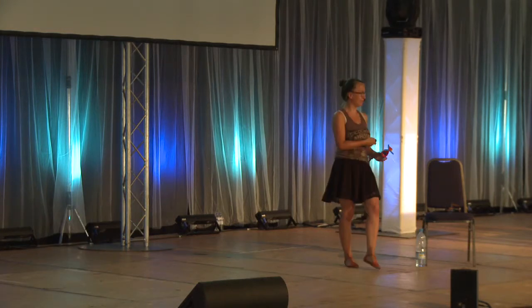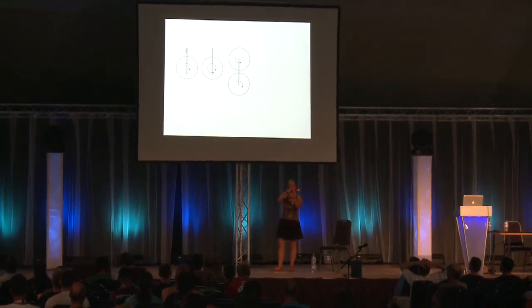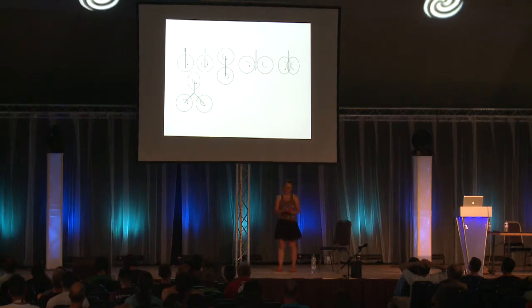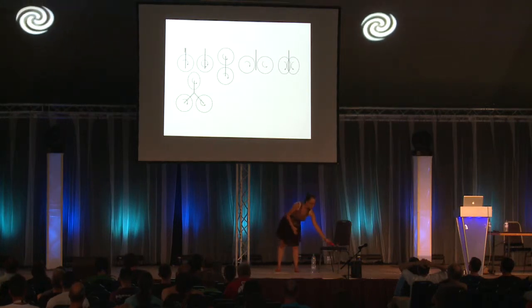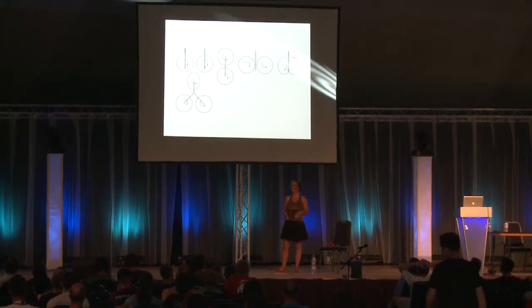But there are different approaches as well. You can add a second rotor below this rotor, a second rotor at the back, or a second rotor next to this rotor, and they are always turning in the opposite direction. As well, a pretty cool setup, you just use two that interlap, like the whisk of an electric mixer.